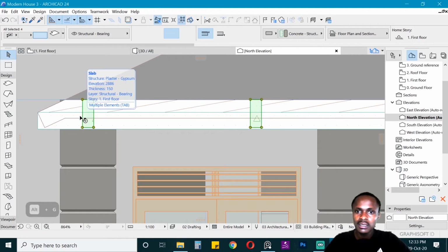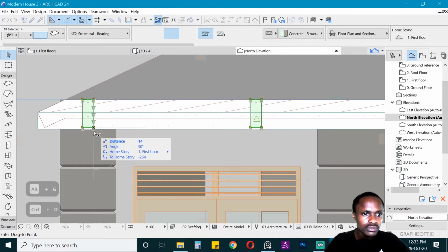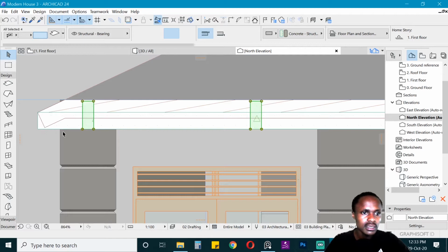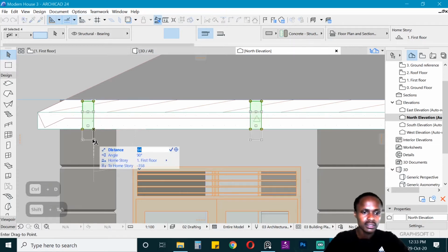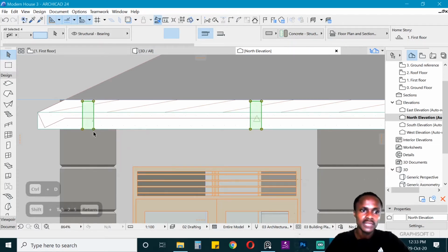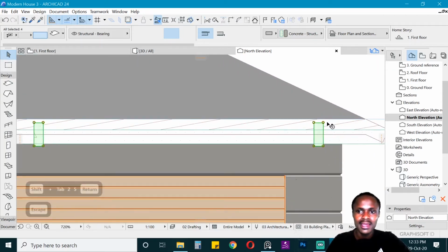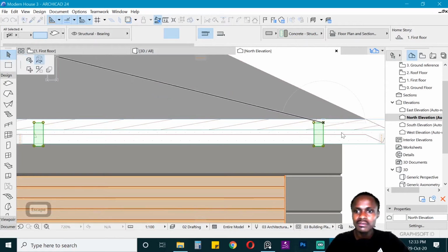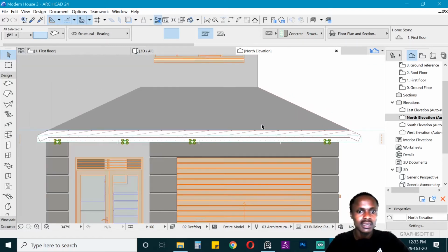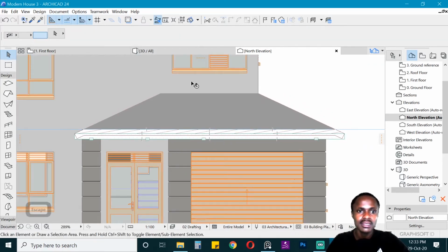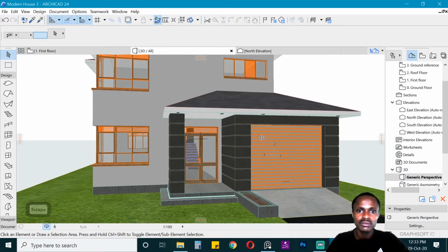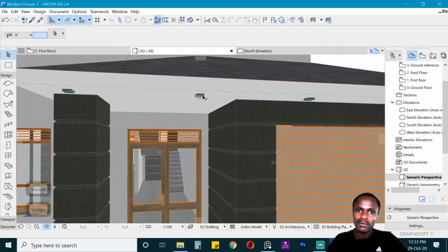But then we can Alt G to be able to see what we're doing. Of course, from 0, from this roof, you want the light to be about 25, just to reveal. And this is too high, I think, for the height of this. It's a recessed light, so it's probably about there, and that is pretty much it. So in 3D, this is what you have.